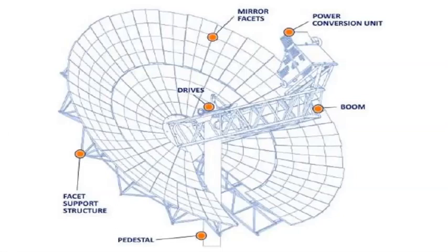The absorbed heat drives a Stirling motor, which converts the heat into motive energy and drives a generator to produce electricity. If sufficient sunlight is not available, conventional heat from either fossil fuels or biofuels can also drive the Stirling engine and generate electricity. The system efficiency of dish Stirling systems can reach 20% or more.